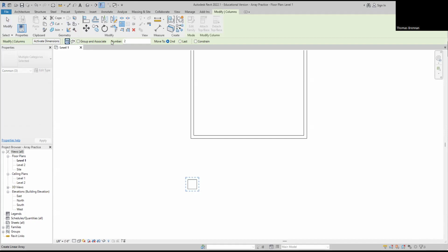Then over here, you're going to choose the number 4, a total of 4. And then we want to tell it we're going to select the last location, so we pick the first place and then the last place. So click on Last, and watch this. Now we have to tell it where we're going to start from. Take your cursor over the top of it, and you're going to see a purple triangle right in the middle. We're going to click there.